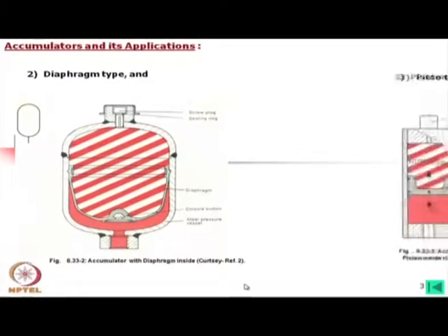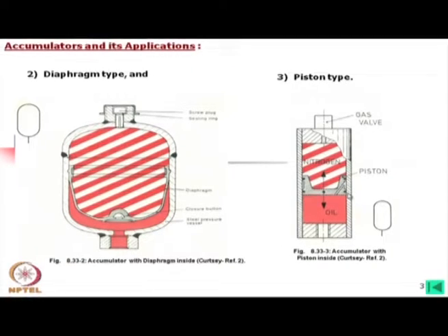And the third one is the piston type. In this case, we can imagine a cylinder, whose inside bore is finished to accommodate a piston. This piston has no rod, then oil is injected from this side and the gas is charged from the other side. So, this works in the same fashion, but here also this works for very high pressure, but